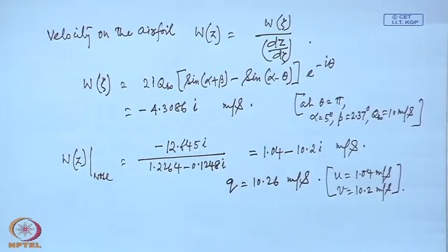I think I earlier told you how the pressure acting on a body is measured. You have not done any experiment as yet. See, on the surface of a body, a very small hole is drilled, okay, and then some probe, usually just a tube, is inserted through the body, so that it is flush to that surface.